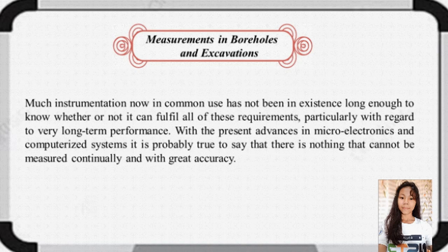Various types of instrument at the site investigation stage may also be used during and after construction for the measurement of certain geotechnical parameters, for example, pore water pressure. Continuous measurement from before construction, during construction, and after construction constitutes monitoring of the measured parameters. This is where the design optimization, provision of information upon which to base design changes or to confirm design assumptions, and the use of completed structures to monitor performance happens.